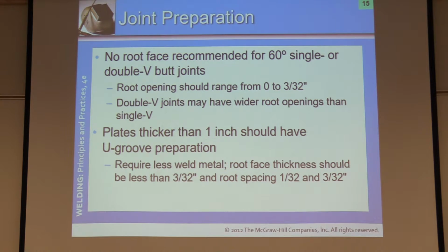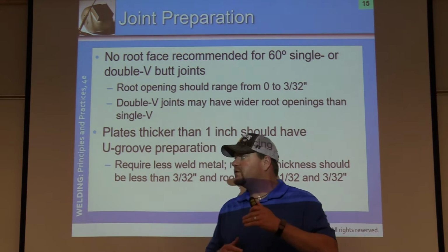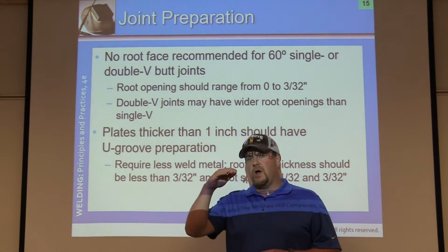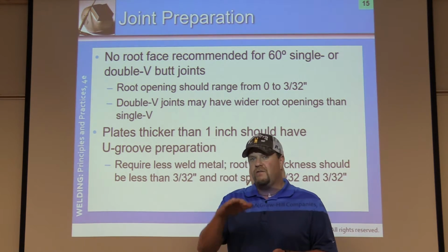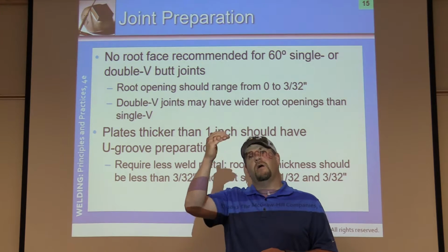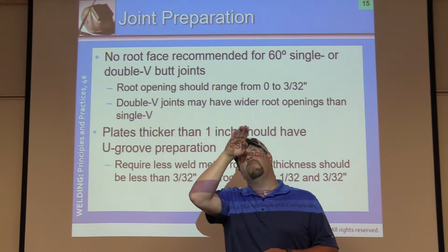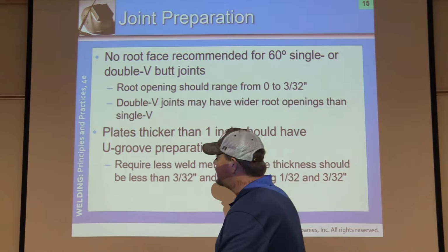Joint preparation, no root face recommended for 60 degree single or double V grooves. So here we go. Here's back into it. And when we get into the shop, like I was telling you earlier, I will show you what I prefer, and a lot of it's going to depend upon heat values, what mode of transfer we're using, and then also how gravity is working for me. Naturally flat, it's going to sink in, so I want a little bit heavier land. I have to think about that. Versus overhead, I'm going to be fighting it, so I need no land, no root face, and I want to be angled back in, pushing it in, kind of keyholing and making sure it's fusing along that top edge as I walk along it, okay?